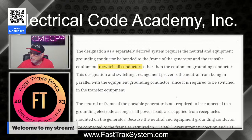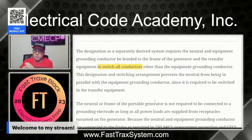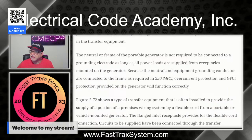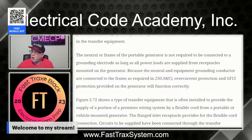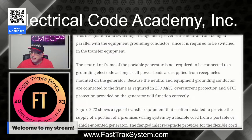Okay. I'm going to make sure that we at least hammer that home, that switching of the neutral is very important in determining whether or not your generator is separately derived or not. It plays a critical role in that. Now let's talk a little bit more. It says the neutral or frame of the portable generator is not required to be connected to grounding electrode, and we talked about this, as long as all power loads are supplied from receptacles mounted on the generator. So the neutral or frame of a portable generator is not required to be connected to any electrode.